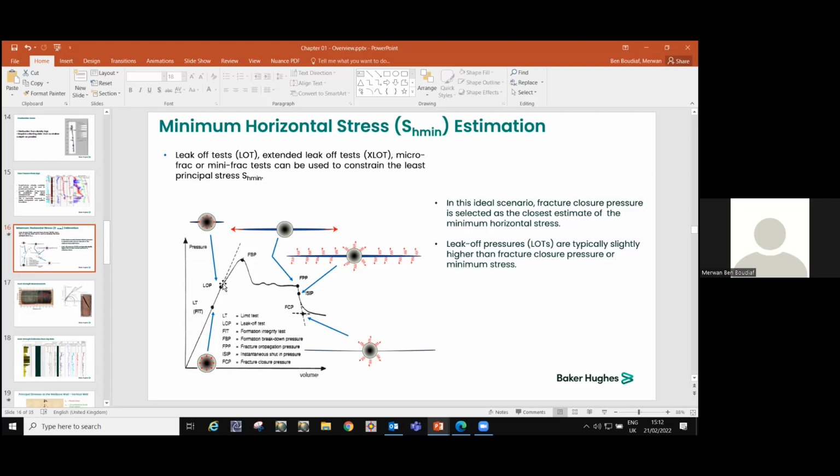Because in wireline, for example, you are running tools in open hole. You need to understand that in some kinds of formations, leaving the tool static can be problematic and can cause a stuck tool. And usually in wireline, because it's a very thin cable, when you have a tool that is stuck, it usually ends up with a loss in hole, and you have all the problems related to this.